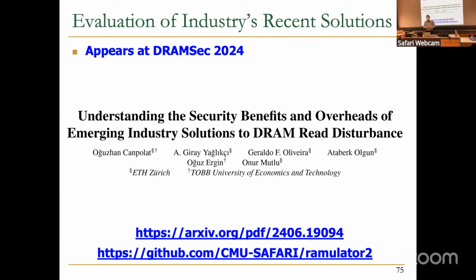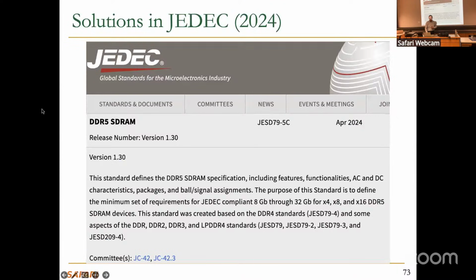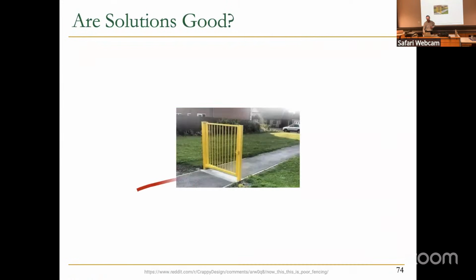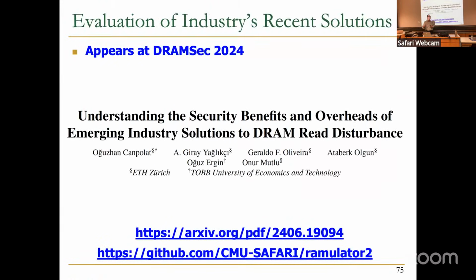Basically, one of the issues is incrementing the counters, the way they implement it or the way they suggest it. If you implement it not so carefully, you increase the latencies. And in the DDR5 standard, they basically change the latencies to increase. Some of the latencies increase because you need more time to increment these counters internally inside the DRAM. And that turns out to be not so good in terms of performance. We reported some average performance hits, meaning downsides, of 5% or so in this paper.